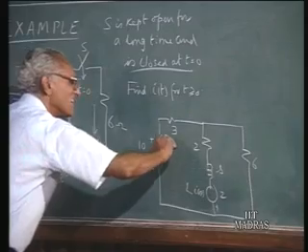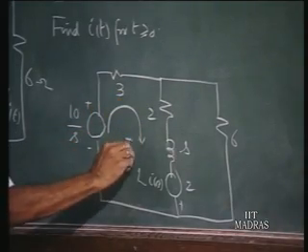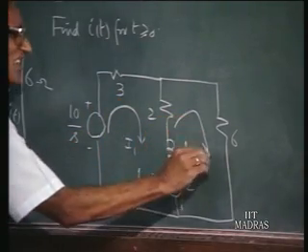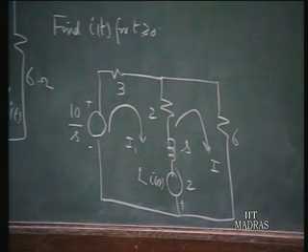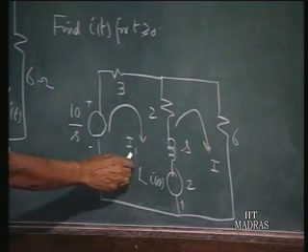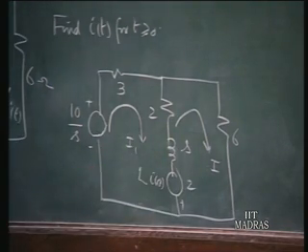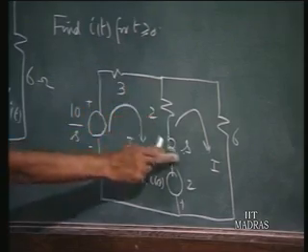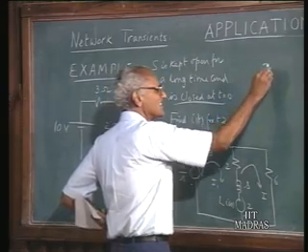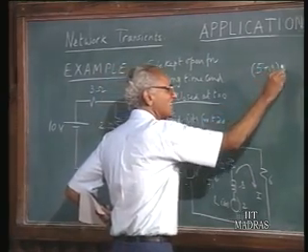So we solve this in terms of the loop currents. After all, once we have the transform diagram, the equations are written down in exactly the same manner as we would do for DC circuits. So you write down the loop equations for these two loops in terms of the variables I1(S) and I(S). I(S) is what we are interested in. So the first loop has total impedance 3 plus 2 plus S, 5 plus S, times I1(S).